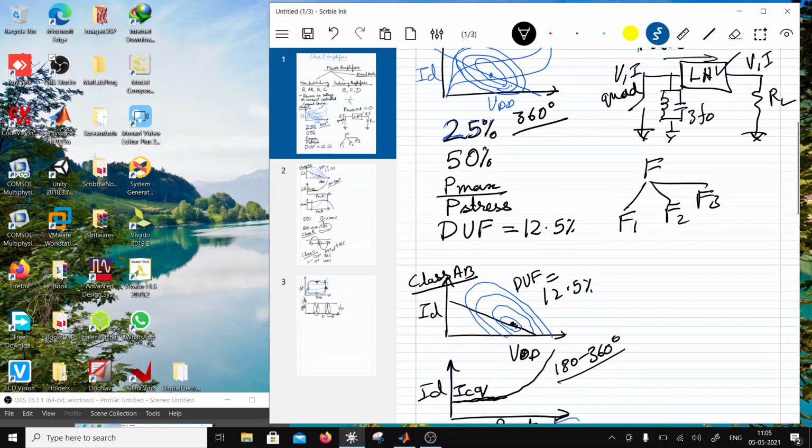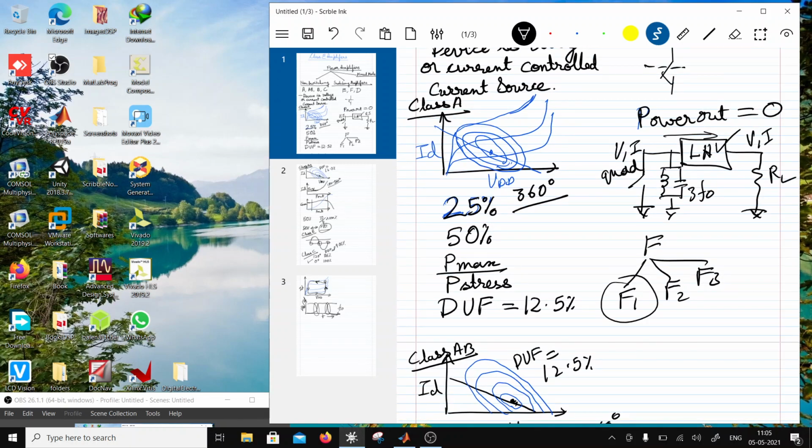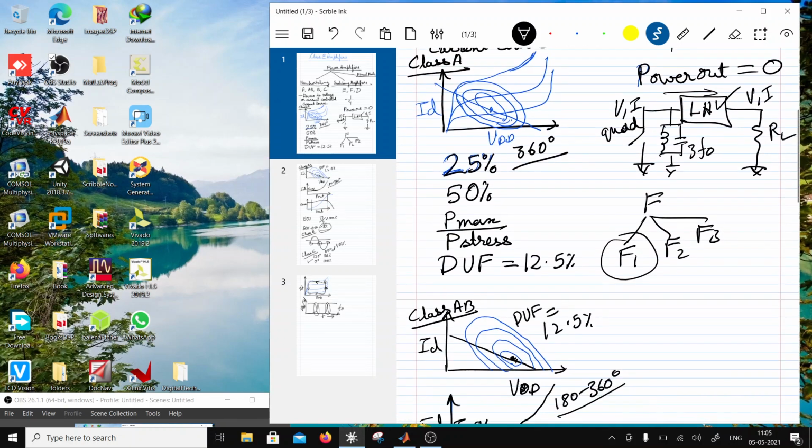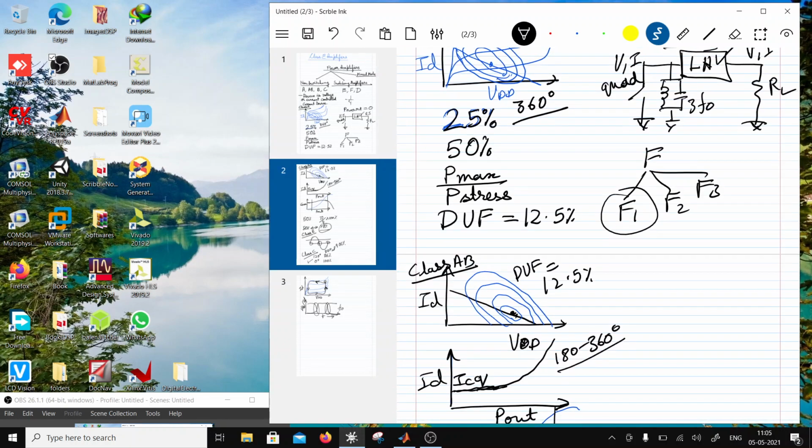So this is called maximally flat class F amplifier, and this is F1. This was patented in 95, I guess. Here the efficiencies are ideally 100% again, because the device dissipation is 0, and the load network is ideal or high Q, right?